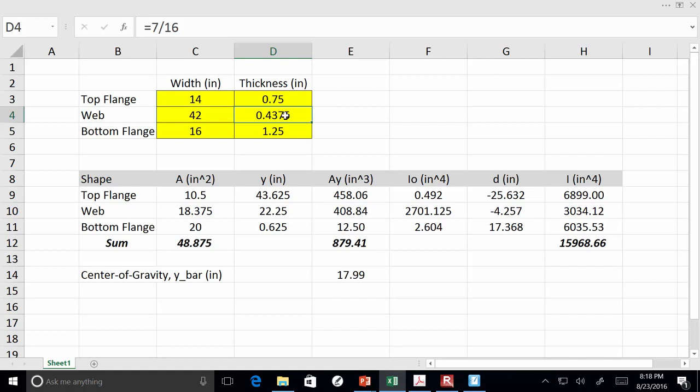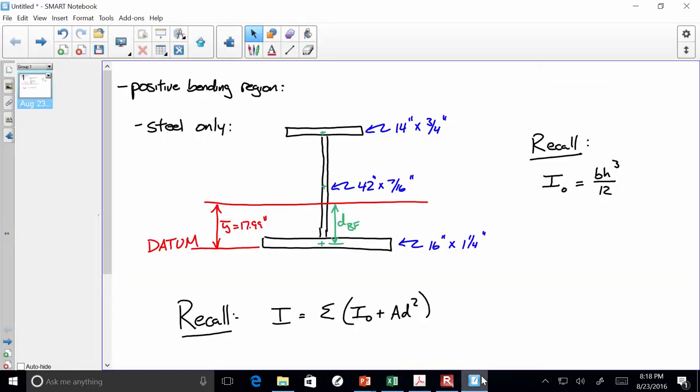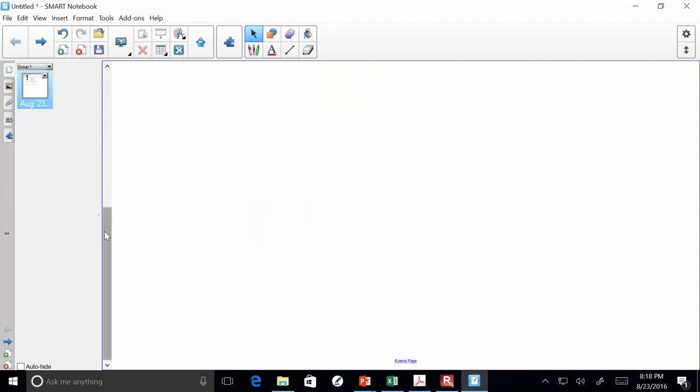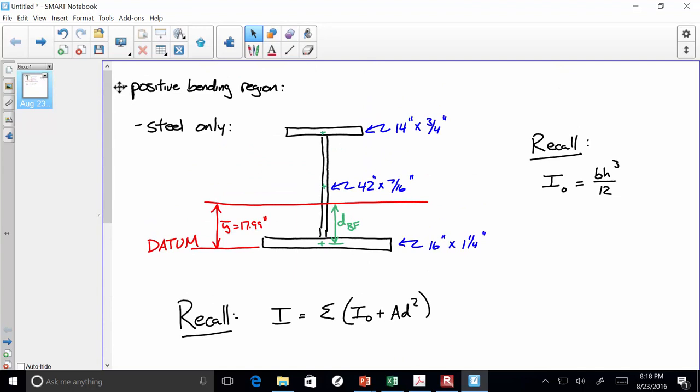Let's look at a composite section. Okay, let's do a composite section. Technically, if we're looking at this bridge, we've got 4 sections that we need to consider. Okay, 4 composite sections, because we've got short-term composite sections, we've got long-term composite sections, but we also have interior girders and exterior girders, right?